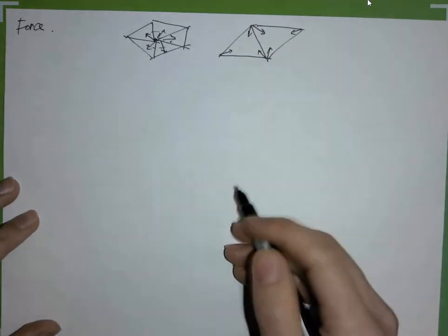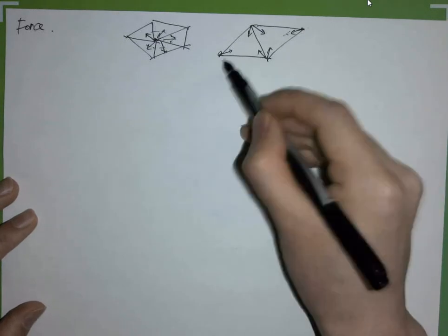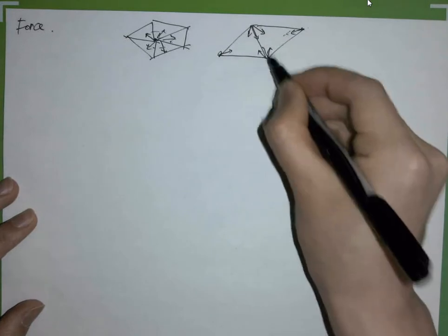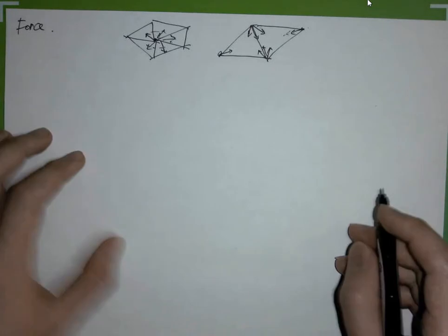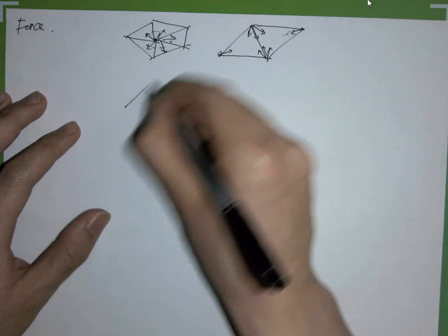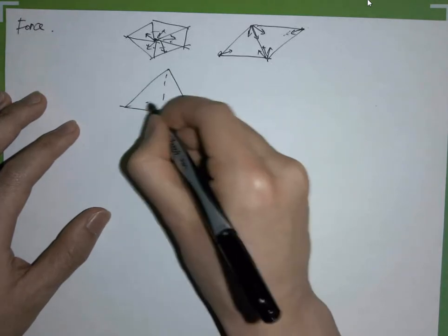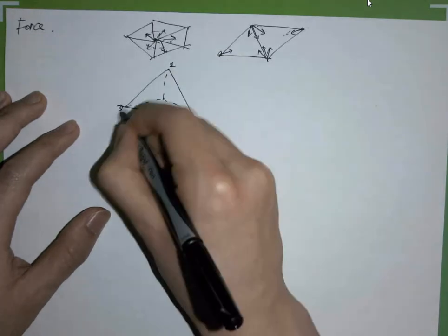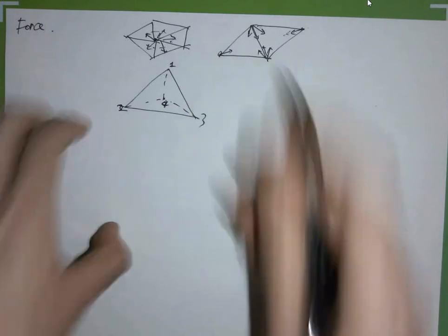Then those two vertices have a force pulling them inside, and those two probably will have the force on this edge, something like this. It's pretty good because we can think about each element as an individual, and once we have the force computed in each element, we should be able to aggregate them together to get the force of the entire mesh.